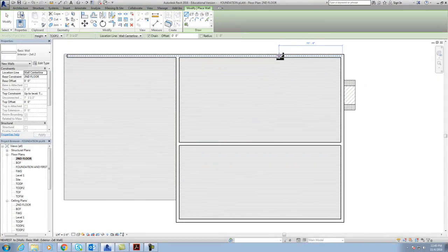And you're going to come in and just remember the minimum requirement for a bedroom size-wise is 100 square foot, which is very small. That's the minimum size for a bedroom. And you have to have a window. You have to have a closet. And you have to have it arc faulted as far as electrical. We're not worried about that right now, though. So when you come in here, I'll let you design this any way you want.